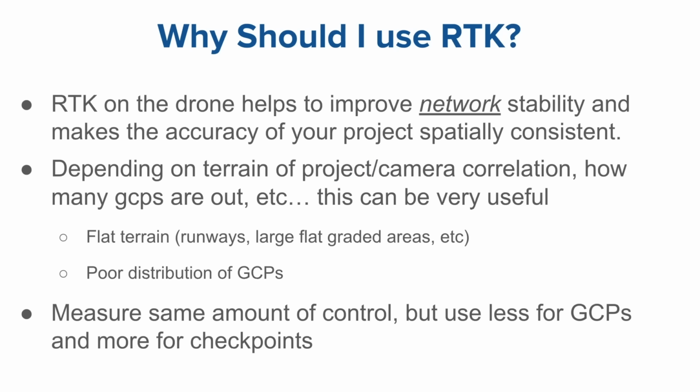Because we can identify issues in the data directly, because we know that the quality of these photo positions should be this accurate, and the quality of these ground control points should be this accurate. And if they aren't, we know that there's a problem, so then it just becomes a matter of figuring out what that might be. It's really nice, because you can narrow down what these issues might be, or what they might be due to.